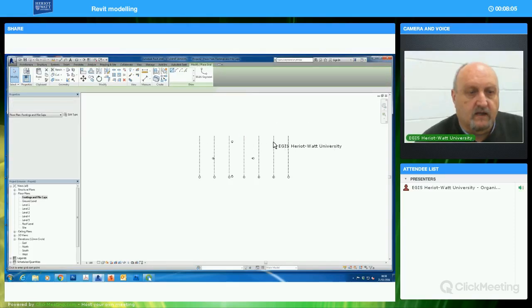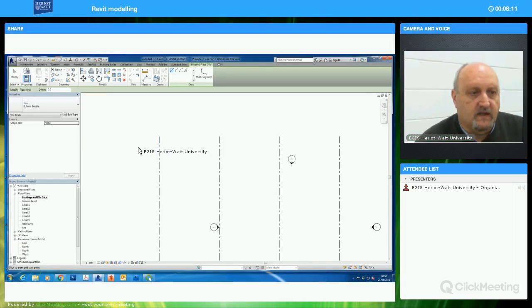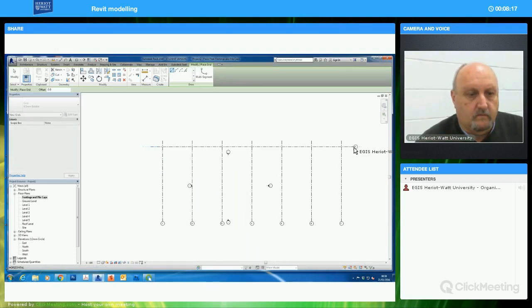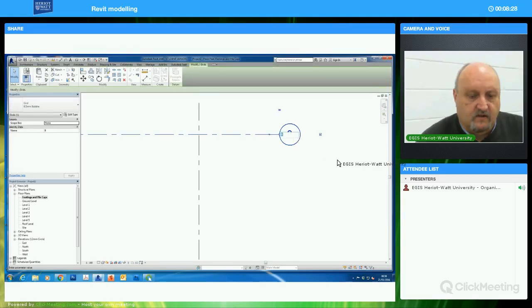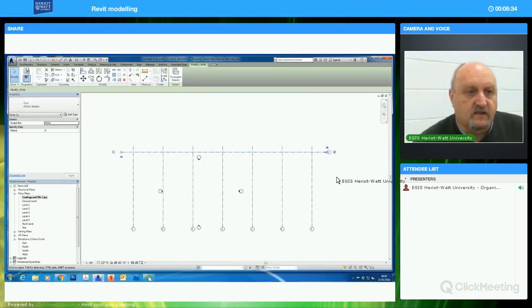I'm now going to put in intersections. Now, please don't do the intuitive thing and start here. I want to make intersections, so I'm going to start here. Hold the shift key down, it'll keep them horizontal. And the software hasn't chosen to change this from the numerical numbering to letters, so I'm going to do that for it, for the first one at least. So that's A, the rest will become B, C, D, etc.